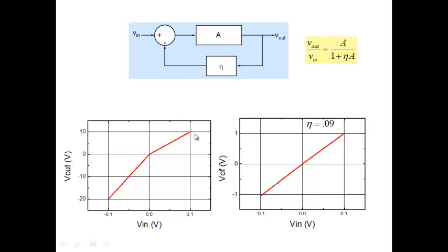Which means that if A's gain is less in the positive direction, the sinusoid here will have a much larger positive amplitude, while if the gain is more in the negative direction, the sinusoid here will have a much lesser negative amplitude. That's the nature of the distortion. Now when it goes through A, those two distortions cancel each other and I get a very nice sinusoid.